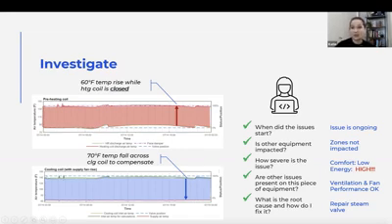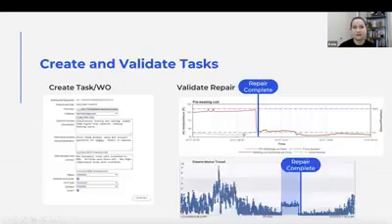So that's why you're above set point: your cooling coil is trying to overcompensate for that, and it can't get there because your heating coil is just going nuts, wide open. So I know I really need to repair that steam valve. So again, I create a work order, I have all the right pieces and parts, and I go out there and I fix the problem.